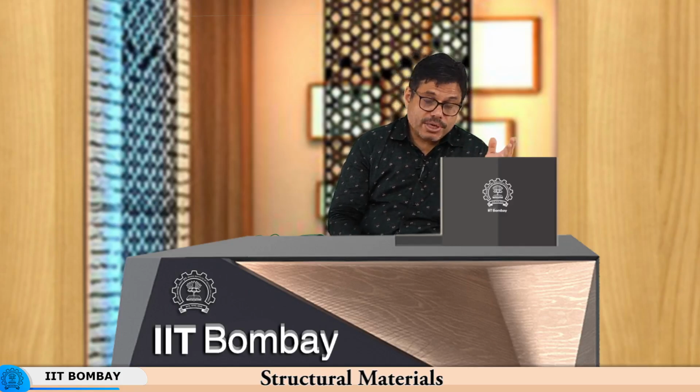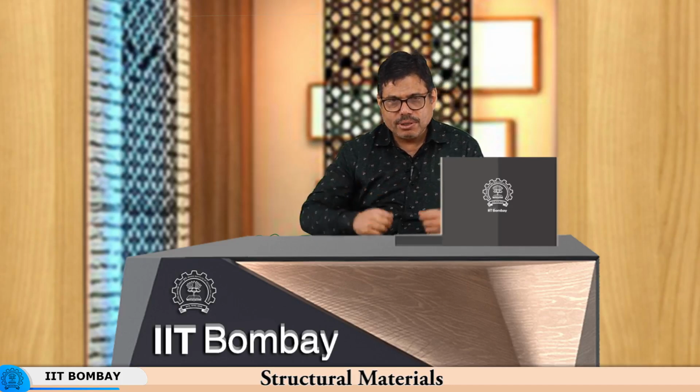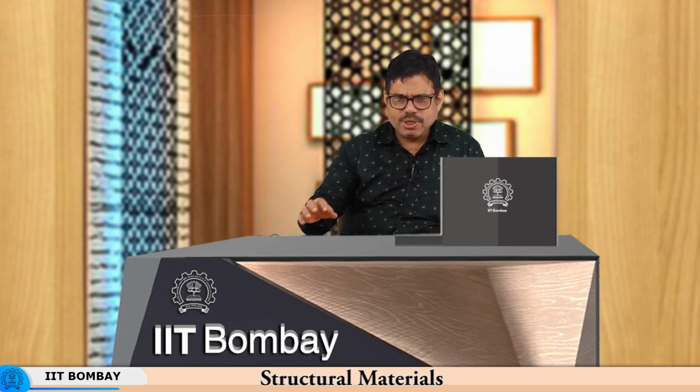So naturally, for critical applications like a lift, or a nuclear reactor or a power plant where failure would mean a large scale disaster, any defect that gets generated either inside or on the surface necessitates the replacement of that part, overhauling of the entire power plant, replacing the worn out parts and so on. That is the reason why there is a schedule for replacement of components, based on the experience that a certain amount of damage could accumulate over a service period.